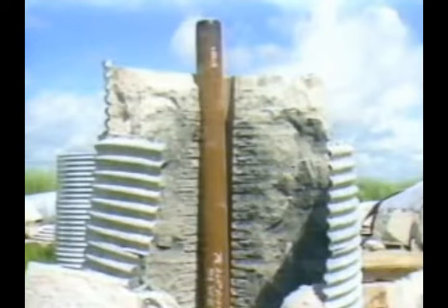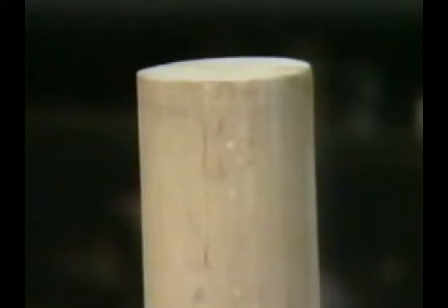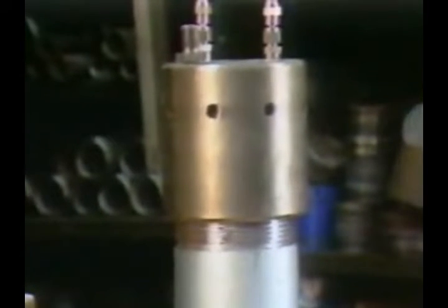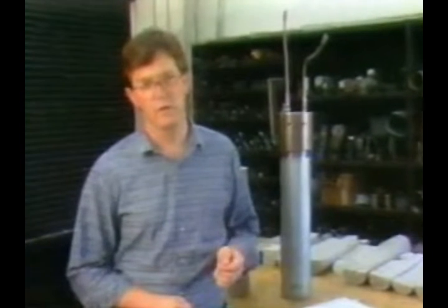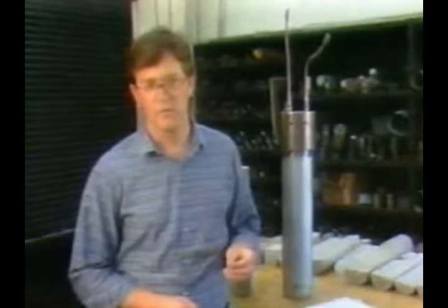Currently, the industry relies on standard testing procedures developed by the API for evaluating well perforators. These procedures include a surface field test carried out in casing cemented within a concrete drum, and a laboratory test carried out using a Berea sandstone target placed inside a special core holder designed to permit flow through the perforation. These tests do not duplicate bottom hole well conditions precisely, so the data on perforation dimensions and cleanliness are not always useful in an absolute sense.